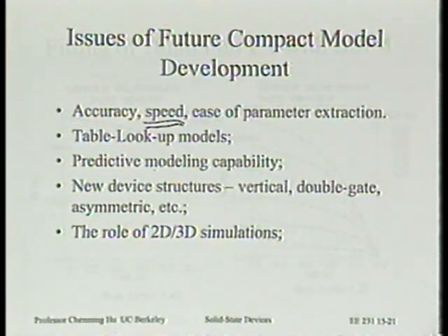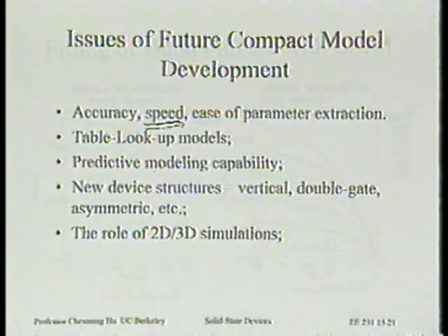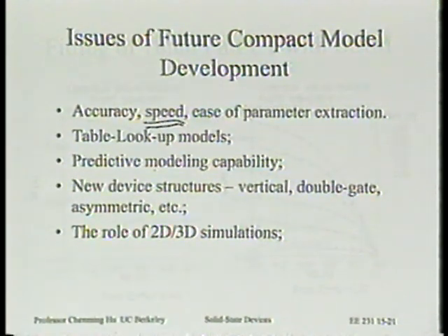But you know what? Those tools, TimeMill and StarSim, they still use BSIM. You first use BSIM to calculate the table for the IV and store those in the table so they can call them out very rapidly. So in terms of accuracy, they still get it from BSIM. And in terms of speed, they just use a totally different simulation routine, not what you understand as how Berkeley SPICE works. And that's how they get 1,000 times speedup, all right?